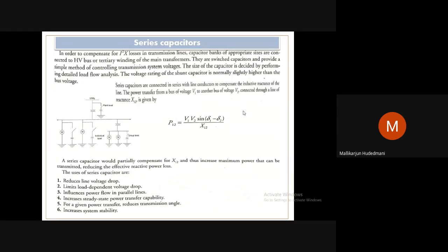This will demand additional protecting mechanism on whose occurrence of a fault compensating devices need to be isolated from the system. This is an additional need for the protection of compensating components, because the compensating components like the capacitors are put in series along with the transmission line.